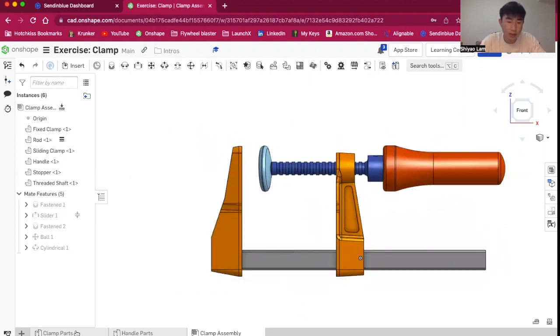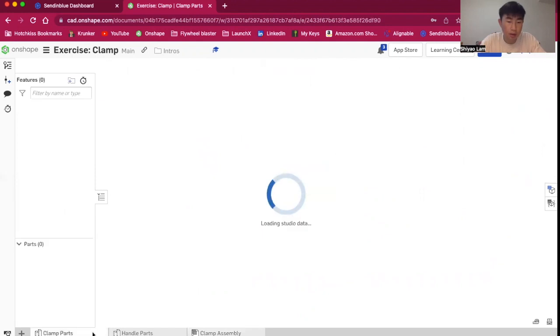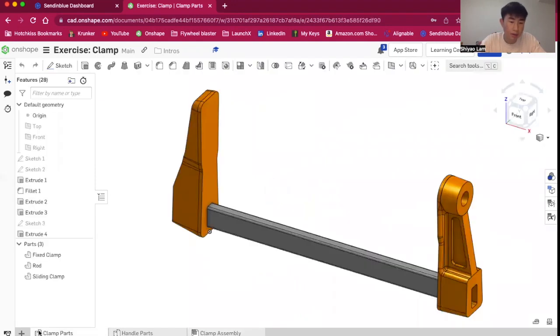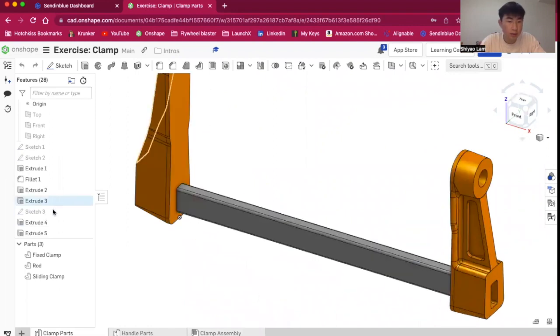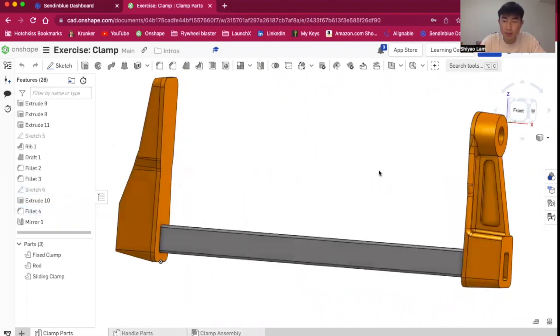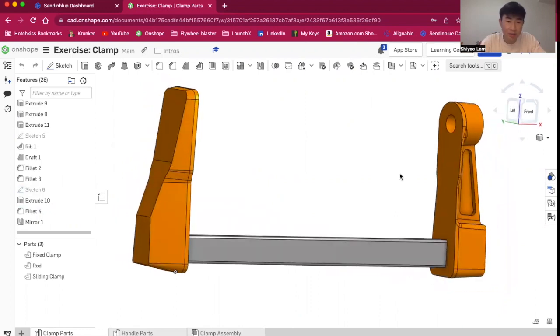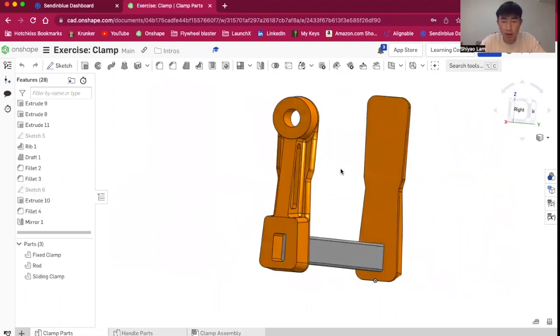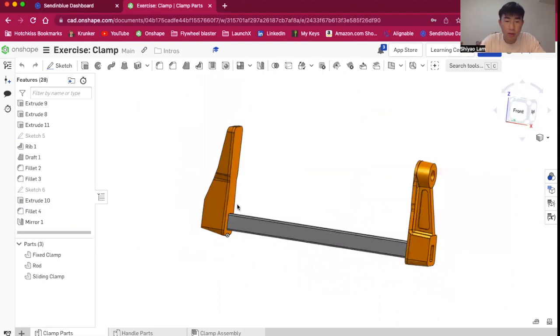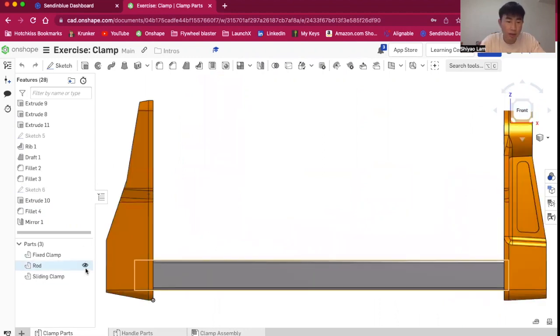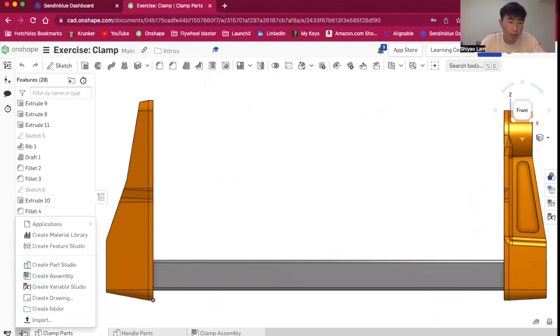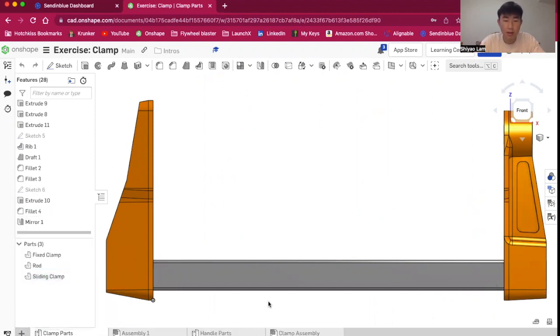And so if you take a look at the part studios, remember, these are called part studios and these are called assemblies. Within the part studios, you see that someone at Onshape must have made these three parts. Although they look fixed, and they kind of are in this regular part studio, if we make a new assembly, remember, click the plus and you can create a new assembly.